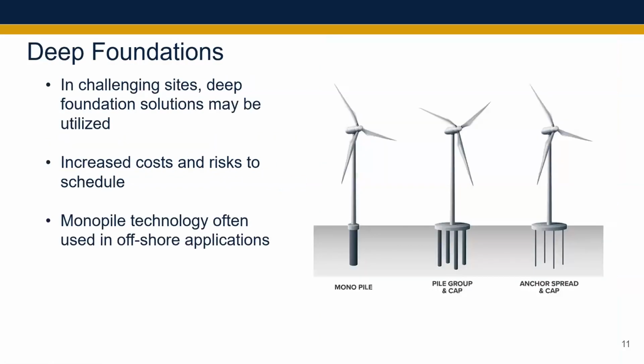The other extreme is the deep foundations. Deep foundations have been used also on challenging sites. A deep foundation solution may be utilized. We all know that as we go deeper, the risk goes higher and the cost goes higher, right? So it's always a question of whether we want to go to a deep foundation. We are encountering more risk and higher cost. Monopiles are more common on offshore wind turbines.